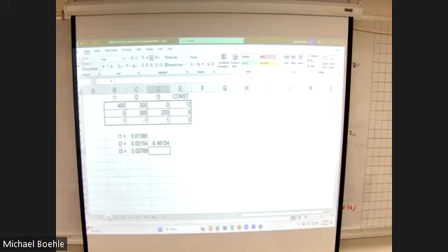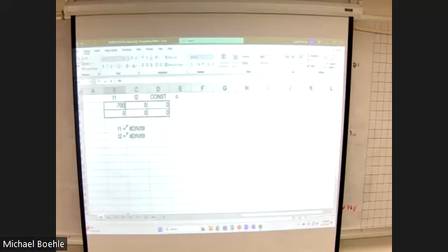We'll come back. So my 2x2 now, my constants are negative 700, 300, negative 12, my current 2, 300, negative 500, and 8. So there you go. 13.85 milliamps for current 1, exactly the same. Current 2 here is equivalent to current 3, but going the wrong way, so it is a negative.